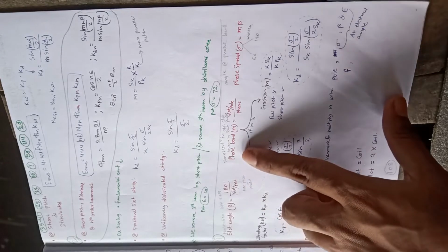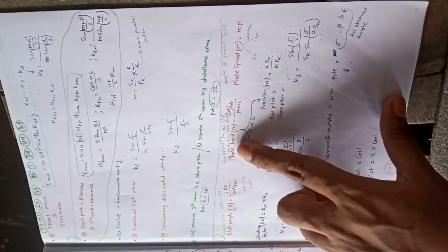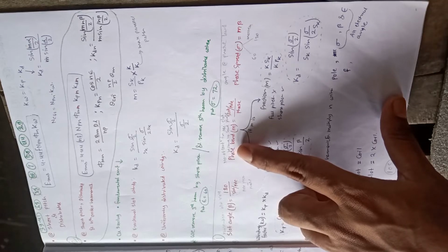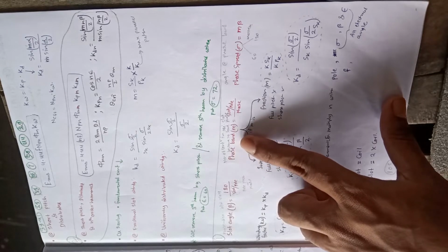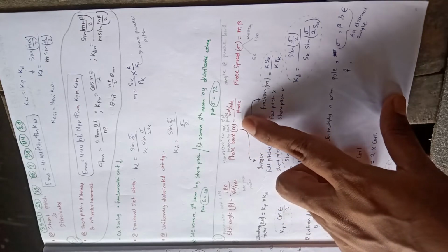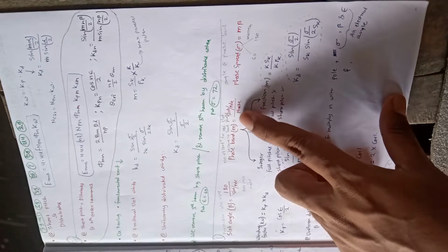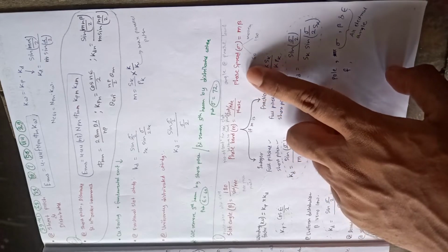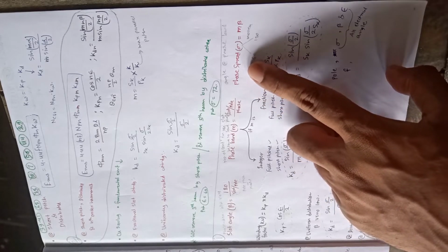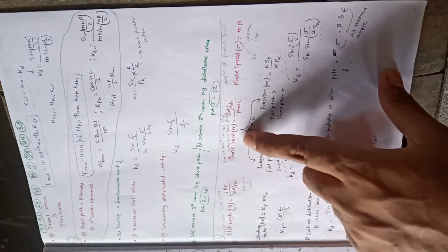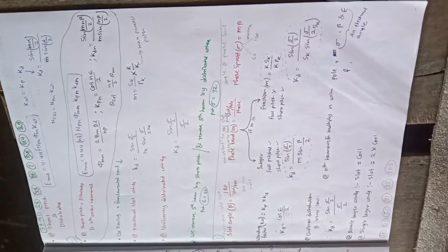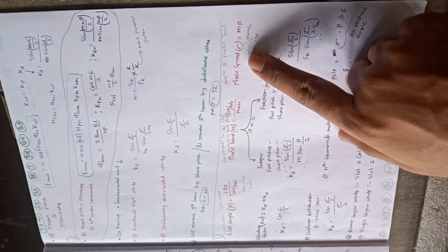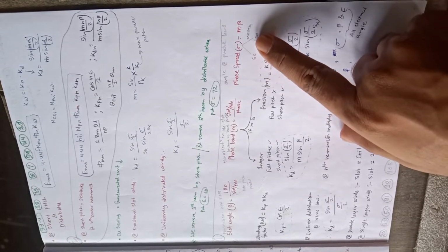And we have phase band M, that is the number of conductors in adjacent slots belonging to the same phase group, represented by M, and its formula is slots per pole per phase, or we can say pole pitch upon phase. And we have phase spread, that is the angle acquired by the phase band, represented as sigma, and it is M beta.